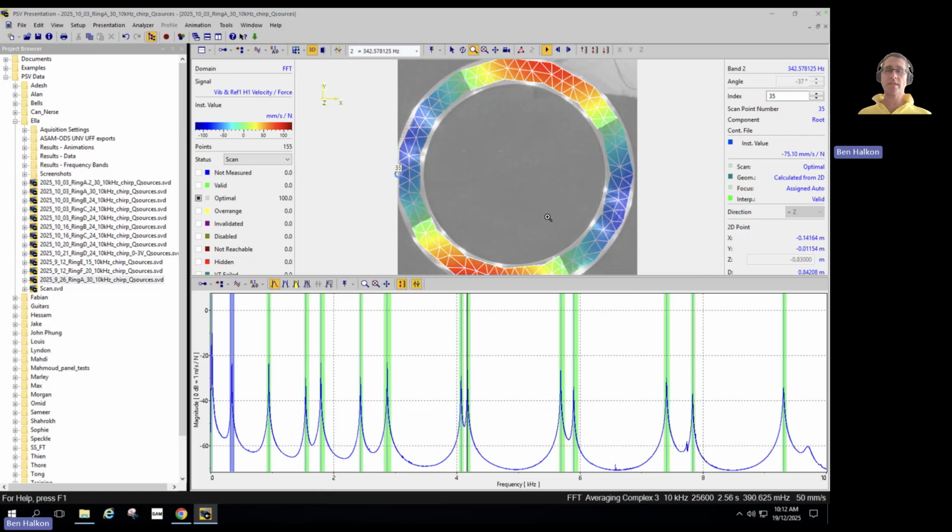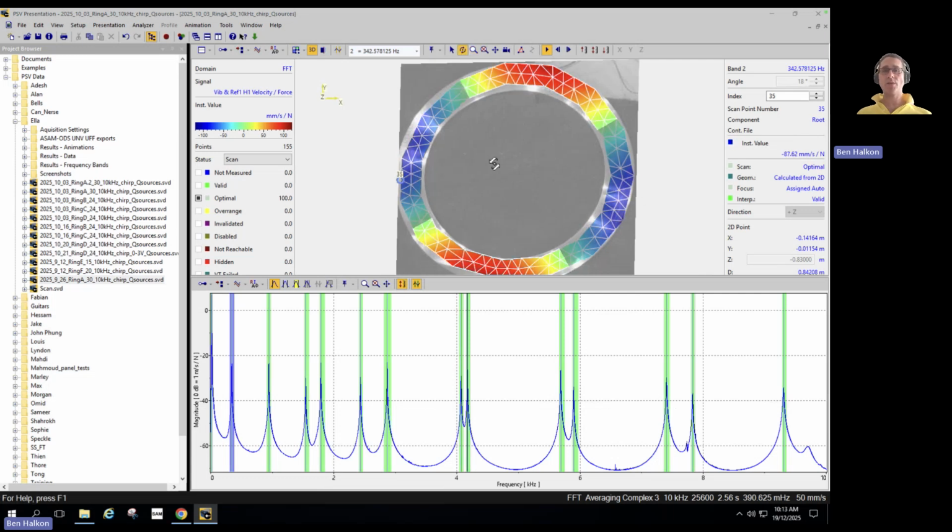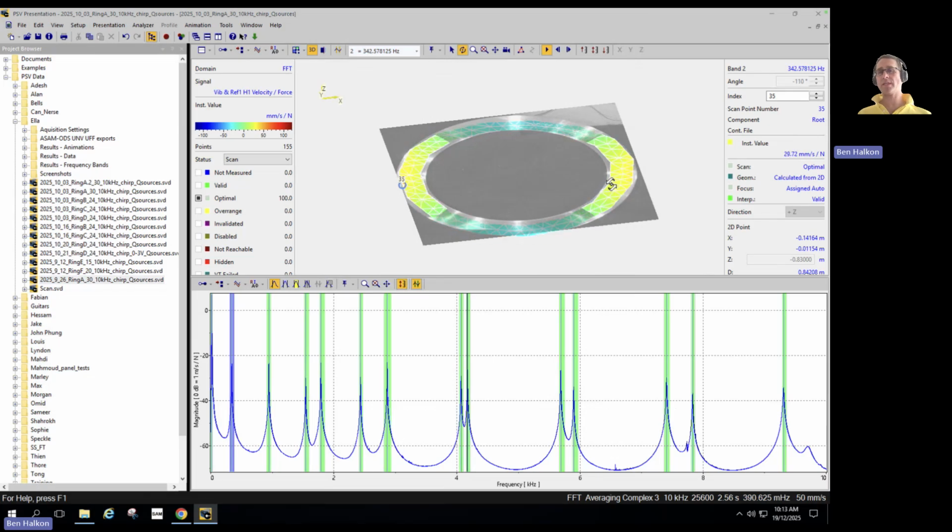It essentially identifies the standoff distance of the target plane from the vibrometer head, and then the X and Y positions of various points that are subsequently defined on the structure to make a measurement grid should be close to being, if not in agreement with, the actual physical dimensions of the disk. Now, we've done some experimentation with this, and we have noticed perhaps that this isn't yet quite perfect. So that's something to check in the future.